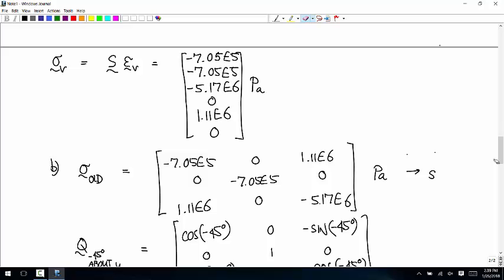So a lot of this stuff is about coming up with independent ways to check your answers, multiple ways to do this, and make sure that it's all basically telling the same story. I mentioned that when I was talking about finite elements: you do your finite element thing, you get numbers, but no one would ever just assume those numbers are right and move on.